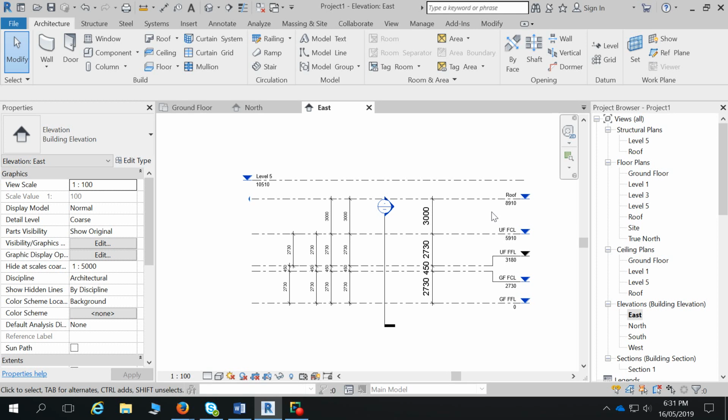So for me, because I unselected make plan view for my upper floor level plan, I don't have a floor plan at the moment available to draw on, which in hindsight is probably a bad thing that I chose that one, but it allows me to show you how to create floor plans from your levels. Just because it doesn't have a floor plan associated to it doesn't mean it's never going to have one. If you want to go to view,